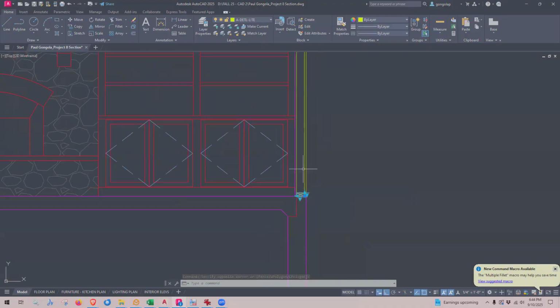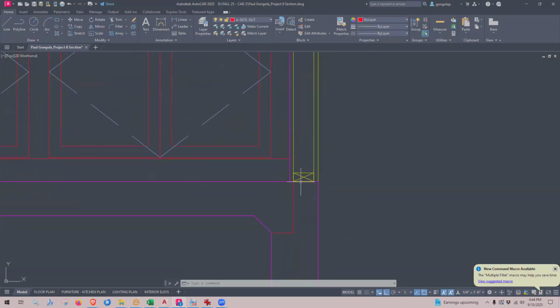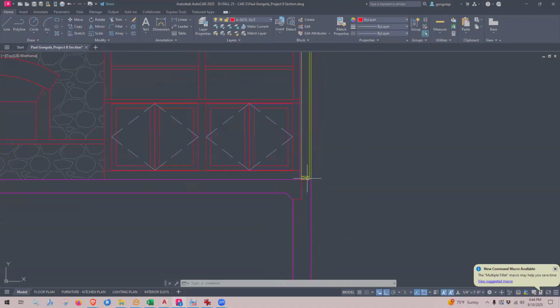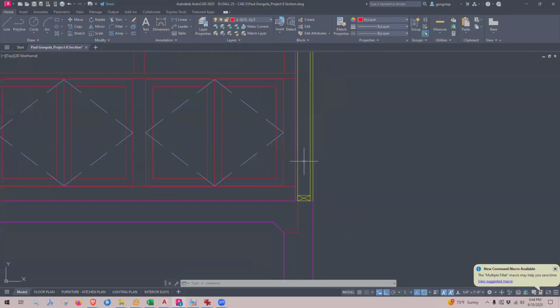All of the vertical studs that make up the wall, you'll see studs at usually 16 inches on center. That means every 16 inches, there's another stud. Those studs get nailed or screwed into this wood sill plate. So the wood sill plate is bolted into the foundation, and then all of the studs above are nailed or screwed into the sill plate. And then the drywall is screwed into the wood studs, and the exterior sheathing is also screwed into the wood studs.